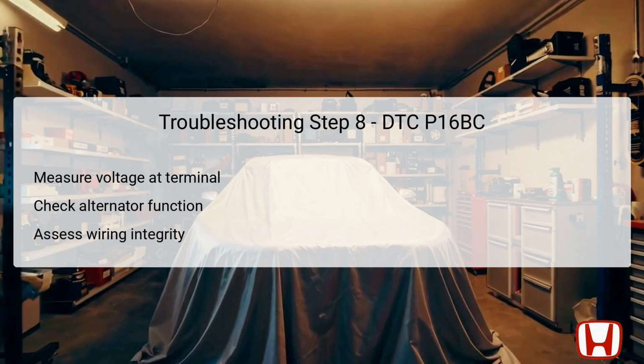In contrast, if no battery voltage is detected, this suggests an open circuit may be present, potentially in the wire connecting the alternator to the number 3 alternator fuse, 10A, found in the under-dash fuse relay box. Effective communication of power between these critical components is vital for the alternator's operational capacity. Ensuring a thorough measurement and understanding the electrical flow is essential for a successful repair and diagnosis.